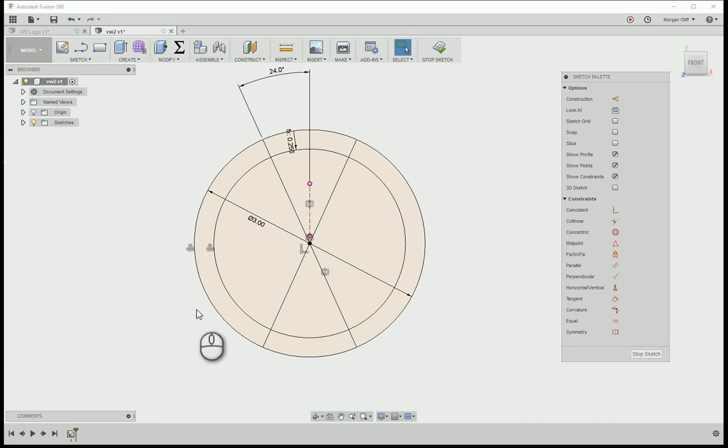Another thing that was annoying me is that these closed faces, these closed loops, flash blue as I'm hovering the cursor over. It's not a big deal, but it annoys me, so I'll actually click these guys to where they aren't closed loops temporarily. Toggle that back. It just makes my life simpler. This actually needs to be construction geometry because they're going to be the center lines that everything sits on.